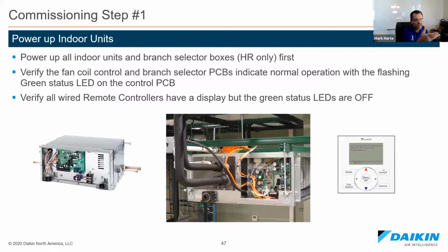Now, I always tell the guys, the first thing you want to do is power up the outdoor unit the day before, because you want to warm up the crankcase heater that wraps around the compressor so we can boil any refrigerant out of that oil. That's the first thing. We recommend 6 hours to boil that refrigerant. You might get a fault code on the indoors because you powered up the outdoor and the indoors don't have power. It doesn't matter. That's not going to bother you.